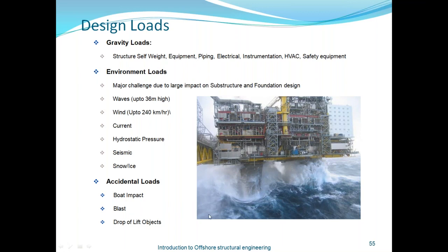But for the residences we are living in, we generally design for self weight. If it's an inner region, it is designed for self weight. If it's a remote area, we'll worry about the wind loads also, depending on the height of the structure. If the height crosses some limit, especially 10 meters and above, we generally worry about wind. Otherwise, for small structures, we'll generally not worry about the wind, and we'll design for the self weight itself.